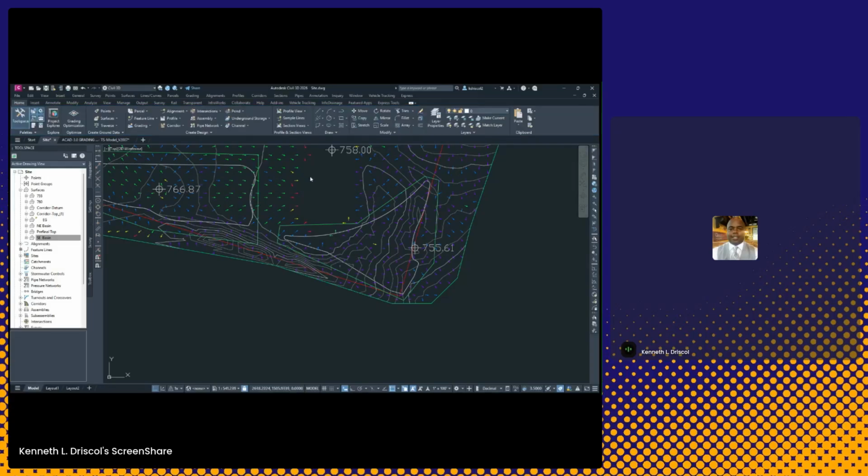From this, I just want to go a distance at a slope. The surface that I want to compare it to in reference to that is this 755 surface. And I'll show you the reason why in a second. So all I want to do is go a distance at a slope. I'll create grading. I'll pick on it. I'll pick the inside. I'll apply it to the entire length. It says a length of 15 feet. That's going to be fine. I'm going to go -5 to 1.